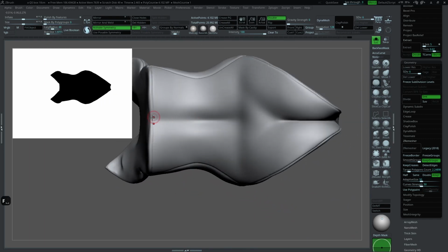You can add it by turning off the symmetry and you drag. You can drag like this, but before you drag, you hold shift and there appears a green line like this. So this is to create a straight line. If your straight line is not right in the center, just hold down space, then move it.